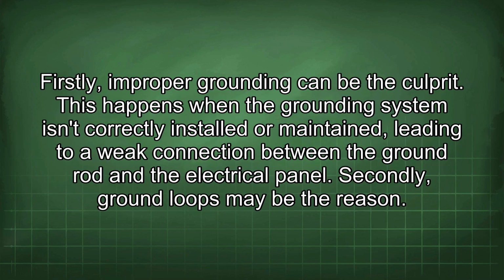Firstly, improper grounding can be the culprit. This happens when the grounding system isn't correctly installed or maintained, leading to a weak connection between the ground rod and the electrical panel. Secondly, ground loops may be the reason.